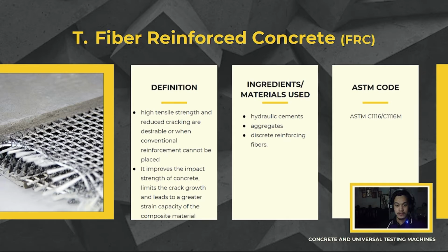Next, fiber reinforced concrete or FRC. It is used where high tensile strength and reduced cracking are desirable or when conventional reinforcement cannot be placed. And it improves the impact strength of concrete, limits the crack growth, and leads to a greater strain capacity of the composite material.